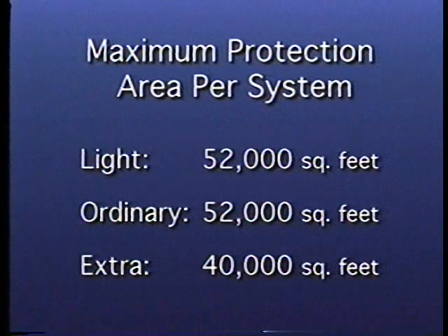The layout of the sprinkler piping installation is affected by the hazard classification, including both the protection area and sprinkler head spacing. There are requirements pertaining to the maximum protection area for an individual system and for an individual sprinkler head. This table shows the maximum floor area coverage by the type of hazard.